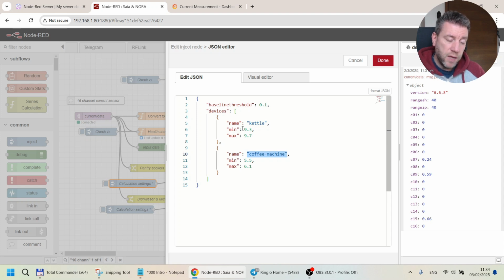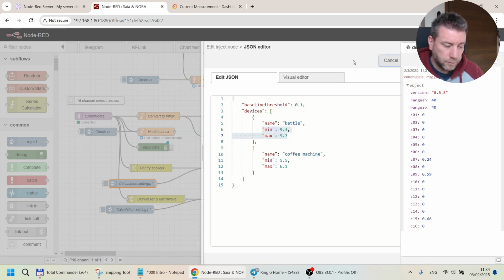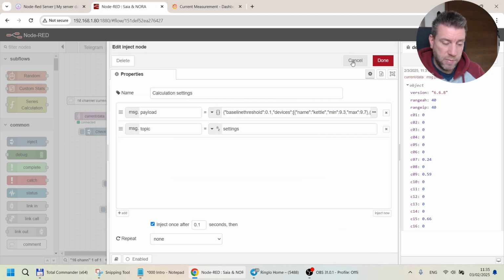And if we fall out of these brackets, but we are still not back at the baseline, say on the washing machine the pump is still running and it still consumes more than the usual baseline, then it just says, this machine still must be working. It's not in that initial 9 or 6 amps, but it's still not back to the baseline, so the machine still must be working. And that's the logic basically.